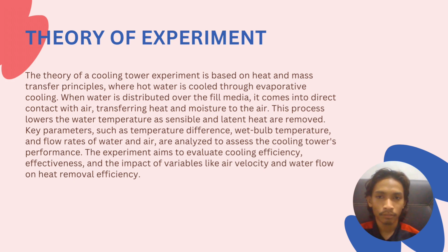I'm going to explain about the theory of the experiment. The theory of a cooling tower experiment is based on heat and mass transfer principles, where hot water is cooled through evaporative cooling. When water is distributed over the fill media, it comes into direct contact with air, transferring heat and moisture to the air. This process lowers the water temperature as sensible and latent heat are removed.